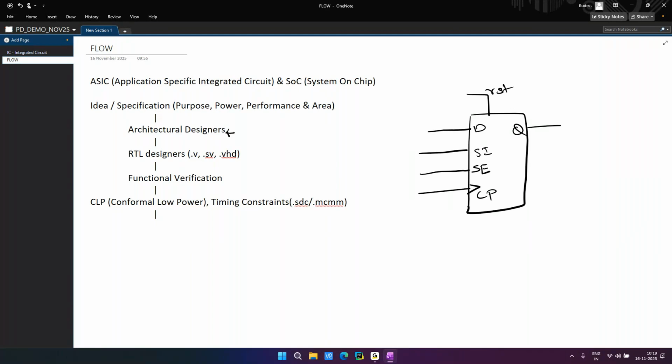Now I'll divide it into small cases. My overall 1 million, I have divided into small circuits. I split it, and now I will validate at each and every circuit output whether I'm getting what I expect or not. Then I can easily find out the root cause. Yes, so that is what DFT will do.